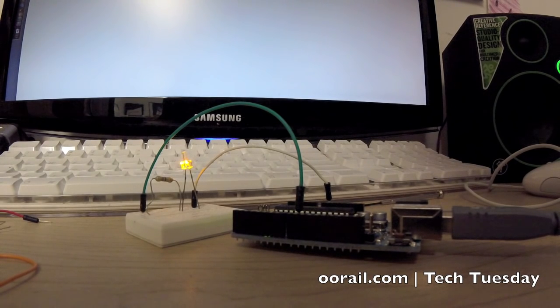So I could show you the reverse of that. If I change the fade amount to say 2, and we'll change the brightness level to 254, and we'll leave the delay, and what we'll do is upload the code. Now you should probably verify the code every time, but since I know this is just a small change and I know it's going to work, I don't really need to worry about that. So you can see now the effect is more gradual. It's going through a much longer number of sequences to fade back, and it's slower as well.